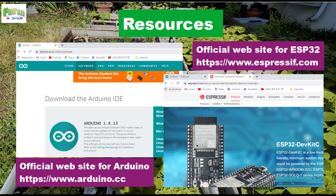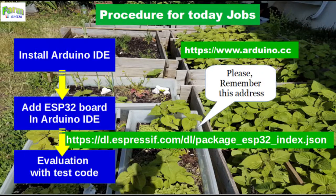The procedure to install the development environment is composed of three phases. One is to install Arduino IDE, another is to add the ESP32 board in the IDE, and the other is to evaluate the installation with a test code. The following video shows you the procedures.